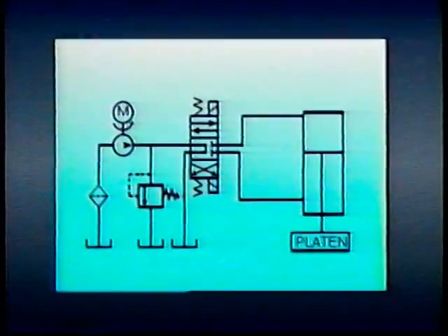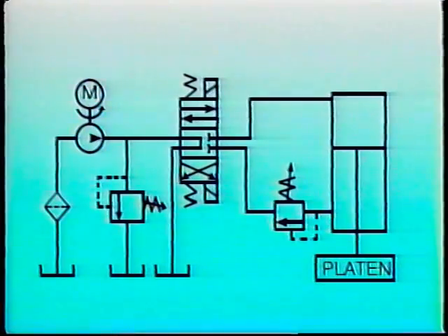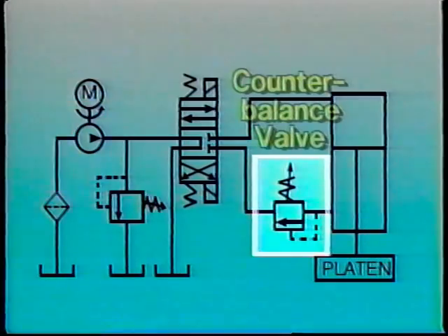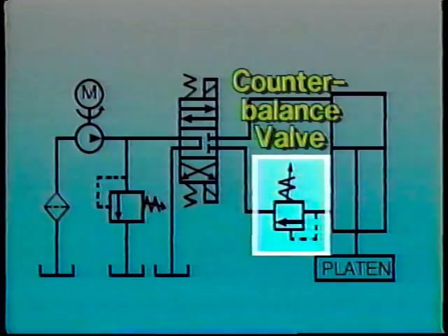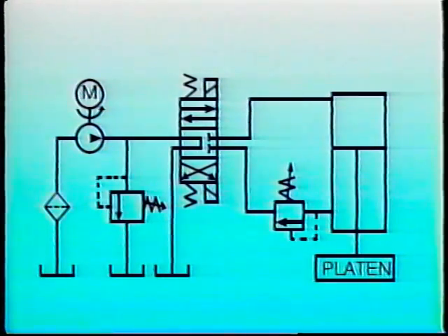To maintain control of piston movement throughout the downward stroke, a normally non-passing pressure control valve is installed downstream of the cylinder. The valve is set high enough so it won't open until pressure at the valve inlet port is higher than the pressure caused by the weight of the platen alone. The pressure at which the valve will open and the platen will descend can be controlled by the setting on the valve.